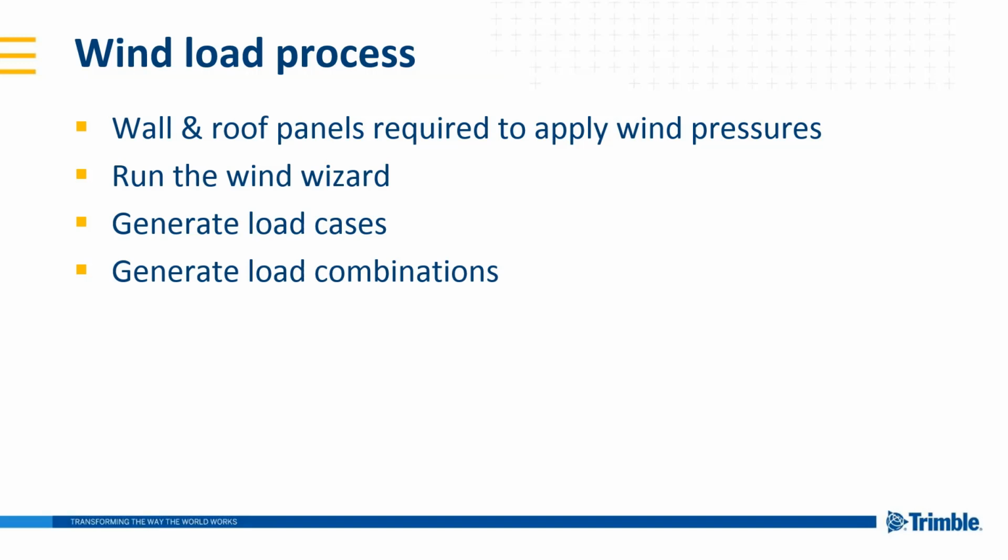Run the wind wizard to input the necessary data for TSD to calculate the velocity pressures, and then generate the load cases to obtain the wind pressures. Finally, you'll generate the wind combinations that the building will actually be designed for.